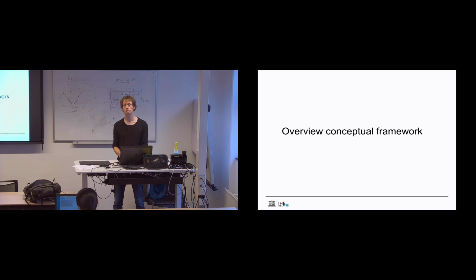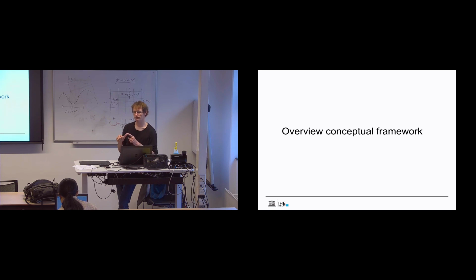You said we will have an idea about how to choose between if I'm going to use Delft3D 4 or flexible mesh. So except for the condition of less than 1. Yeah, the CFL condition. Yeah. What else can be judgmental in this area? Well, for one, the grid creation.